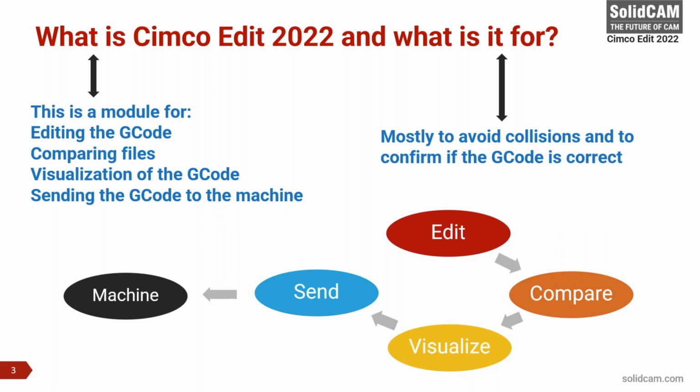Most of the time, this is not exactly what happens on the machine, because between the CL point and the machine comes another interface, which we call a post processor. Now, the post processor can sometimes go crazy. You can have wrong outputs. Something is written wrongly in the post processor, and most of the time the wrong output doesn't happen for linear passes. Most of the time the wrong output comes for the arcs, and that is really very dangerous.